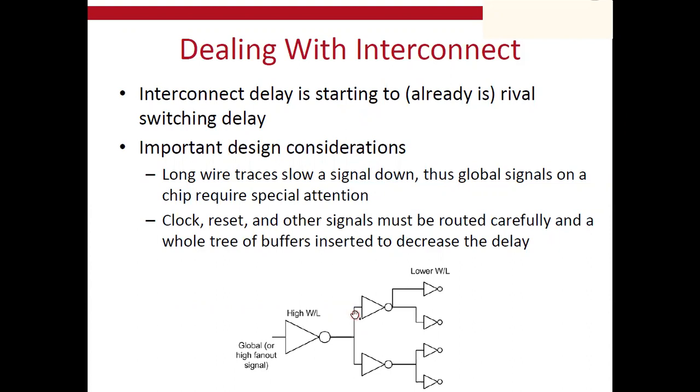Of course, you can manage to minimize this delay by shortening the distance of these interconnections. Usually the cross-sectional area is not a very adjustable parameter in the design, simply because it is related to the technology of fabrication. But the distance between gates, I mean the wiring between gates, is part of the routing, which is part of the layout process. So as a designer, you should act to shorten this distance in order to minimize the interconnection delay effect.